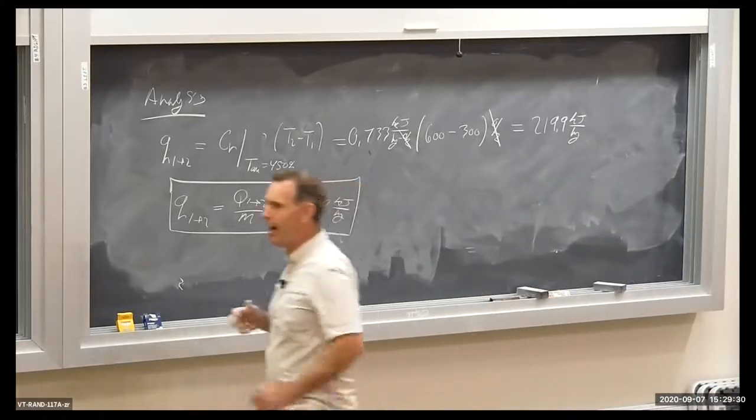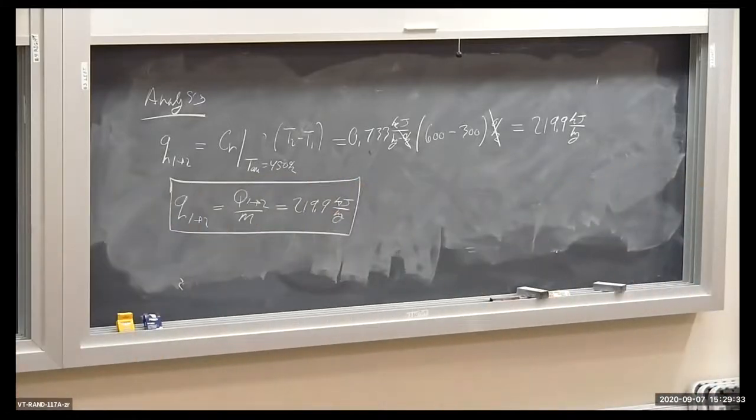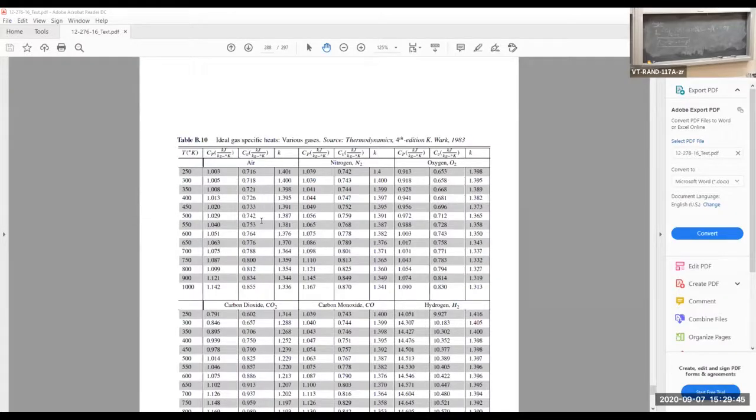And if you look at the tabulated values for specific heat, they don't change that much. So here, let's go back and look. Specific heats for a constant volume process, again, 0.721, 0.776, about a 0.055 kilojoule per kilogram degree Kelvin change, about 10% variation or less between 300 and 600 degrees. So we would expect our heat transfer calculation to be within 90 to 95% accuracy.